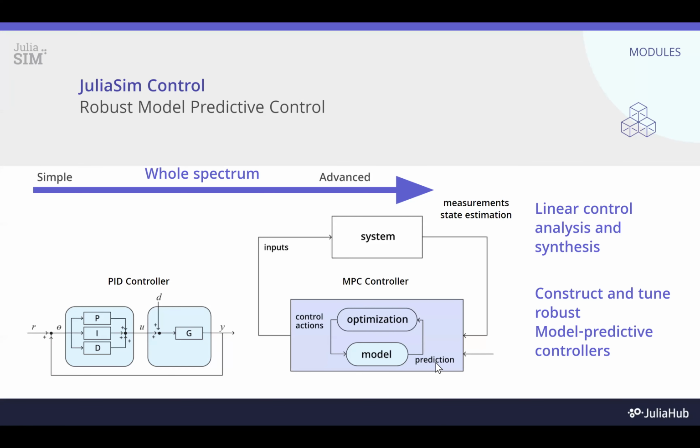into the controller. And now this controller has a model of the system. It has an online digital twin of this system. And this model is used for prediction. So given a measurement and given a state, what is the next likely state of the system given a control action, right? So if you have a space of control actions, what is the best control action to choose such that some objective is satisfied, right?